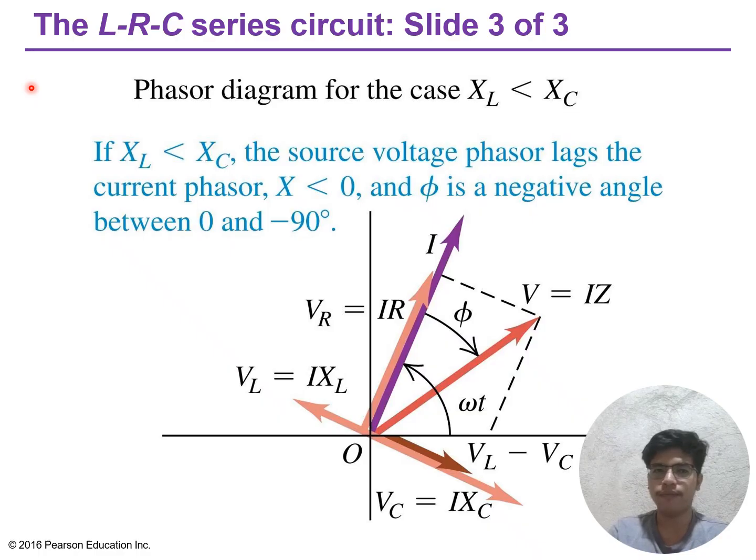with current and voltage perfectly in phase. At very high frequency, inductive reactance X sub L dominates the impedance, making it very large and the circuit primarily inductive with current lagging voltage. So the inductor effectively blocks high-frequency current. The sharpness of the resonance peak, its height and width.